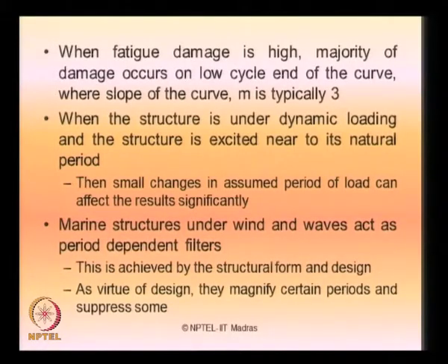So, marine structures under wind and waves act as period dependent filters. That is a very important property, because it comes from the virtual design of a marine system, because we design a floating structure, we design deep draft platforms. So, they filter certain frequencies, okay, they allow only certain frequencies.